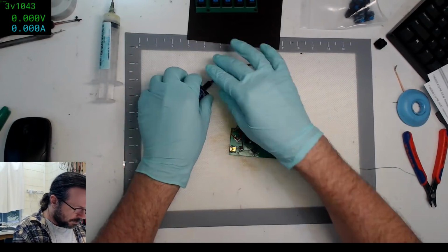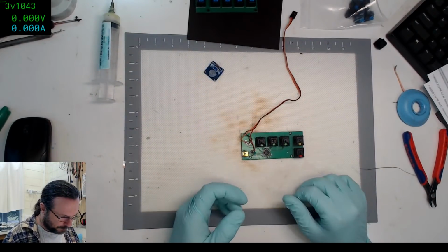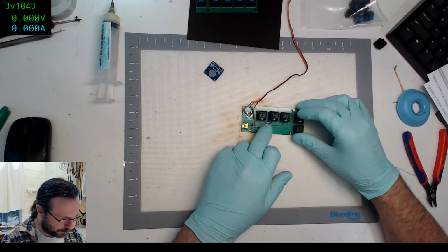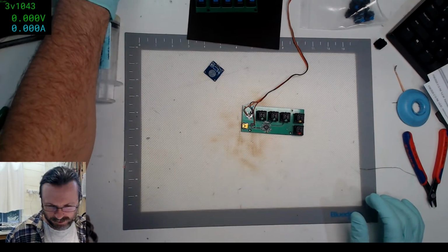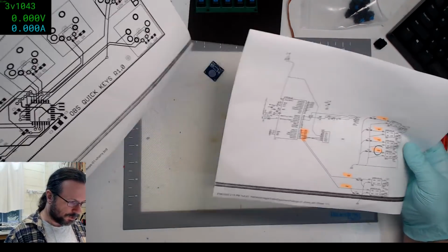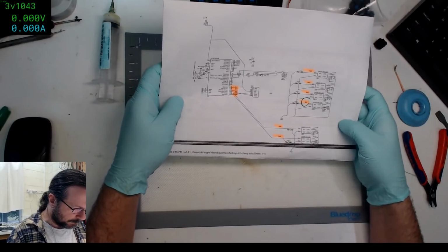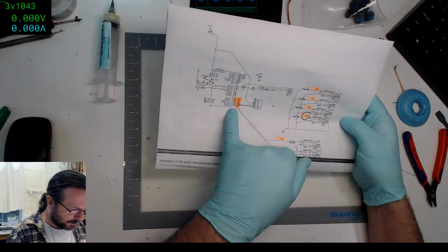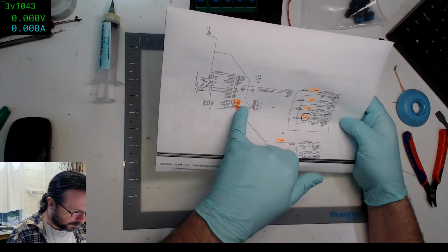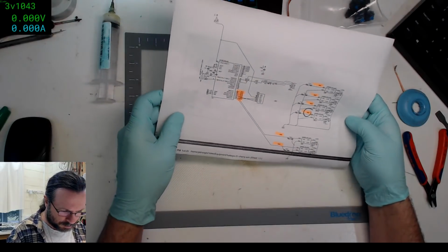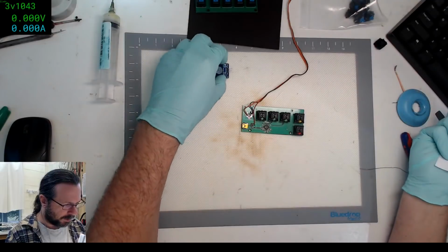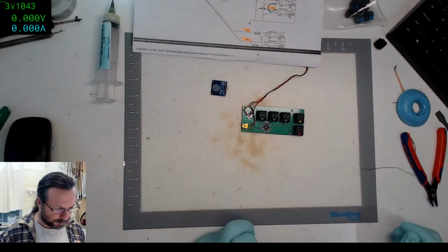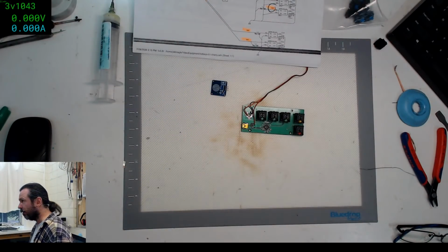Okay. Well, we can't have that actively powered yet, partly because the control line is part of the programming interface. Just due to the way that the routing was done, it ended up that way. We have the programming interface here, and some of the lines are shared. In this one particular, SW4 is the MOSI line, so we can't have that actively connected while we're doing the programming. It's not a problem. Anyway, now I've got to get a programmer and hope that it works.